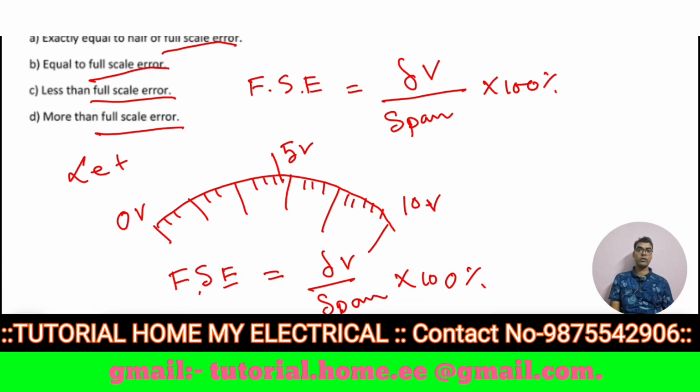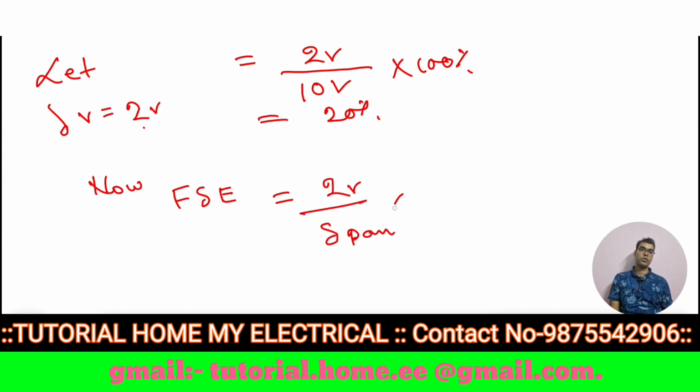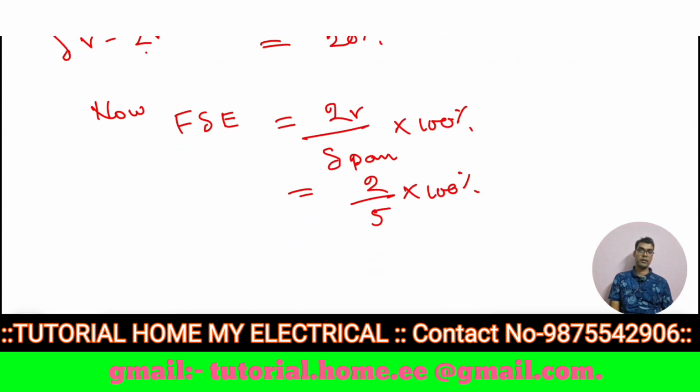Now the full scale error equals 2 volt by span into 100%, so 2 by 5 into 100% equals 40%. So if the span is decreased, then the full scale error is increased.